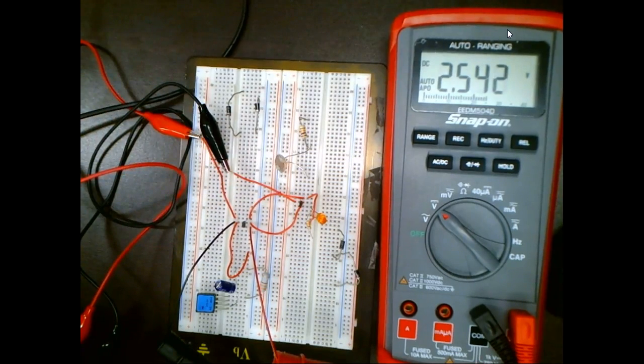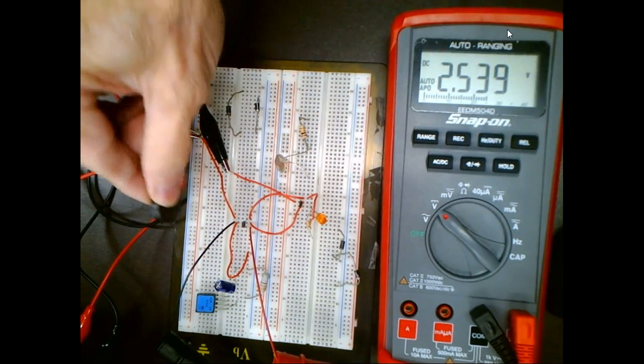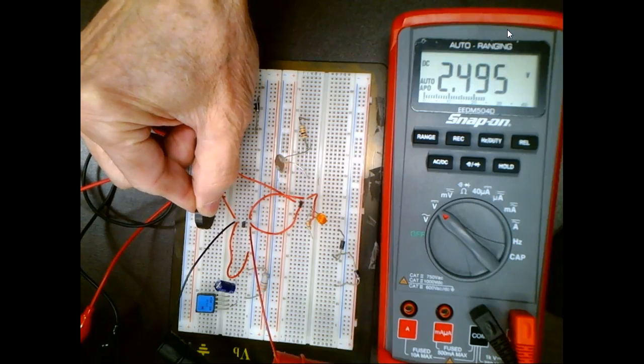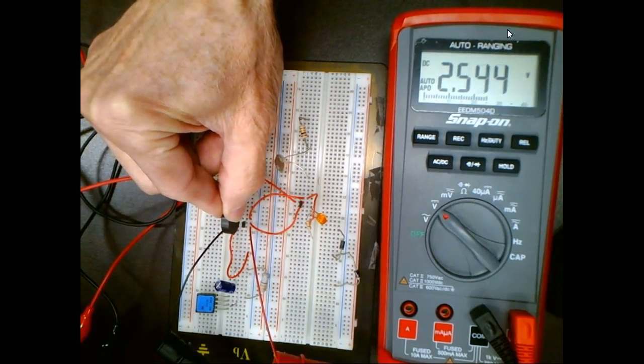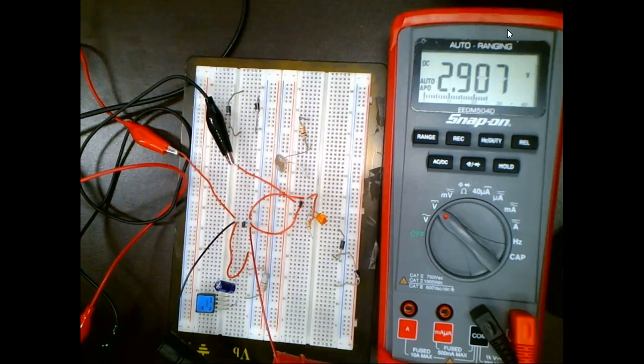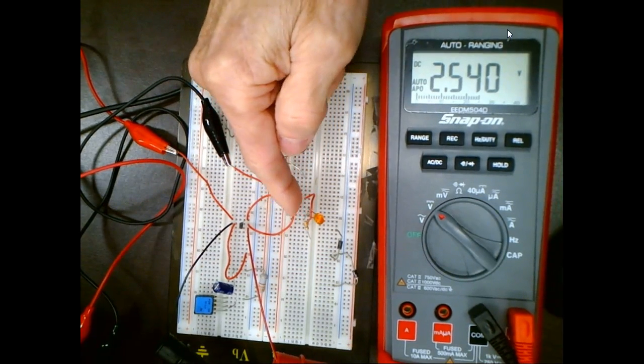So one pole, it starts in the center, so it's like a voltage divider, right? One direction causes that output voltage to go up, and one causes it to go down. So technically with this guy, we could sense the strength of the field. So we could technically sense what? How close the magnet attached to the thing that's in motion gets, and that voltage would indicate a position. Are we okay? This would be considered a proximity switch.